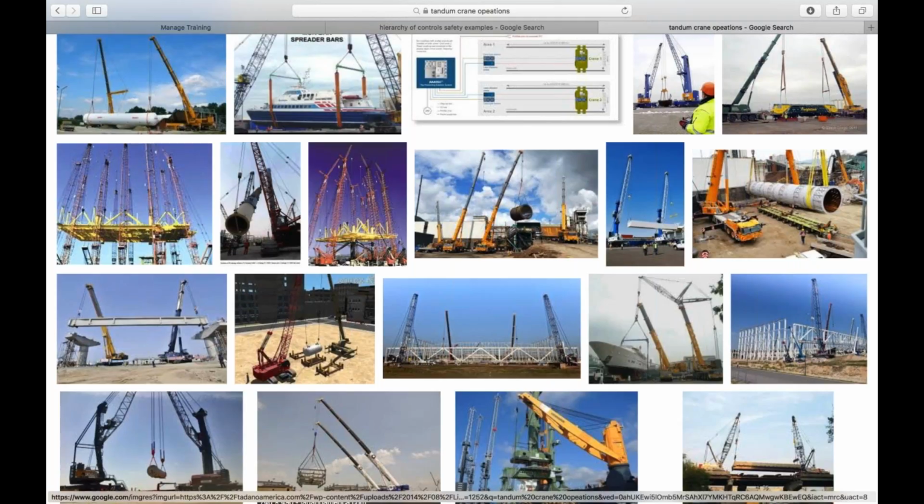Okay, good. So let's move on to 3.41, emergency procedures. What procedures do we have in place or must we put in place for first aid, emergency medical services, fire protection and prevention, and hazardous materials also? We have to take all those into consideration. And then also emergency procedures for rescue from extreme heights, confined space, and trench collapses. If we have a risk of any of those, we have to determine if we're going to use a third-party rescue team, or if we're going to have our own employees, a fire brigade, or rescue team at our own facility.